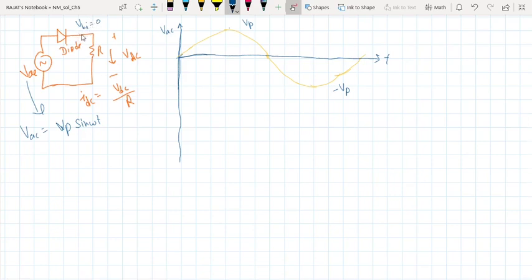So for the power diode case, it is approximately 1 volt, and for the signal level, the low power diode, this is 0.7 volt. Okay, so here what DC voltage is here, so what we will get as the DC signal, I can say the output voltage in terms of time. Here, if you are saying the positive half cycle, in this first half cycle, what equivalent circuit model you will get, this is the question.